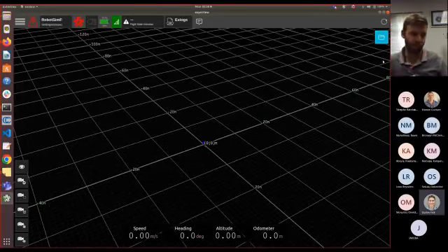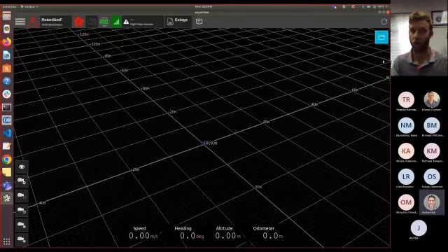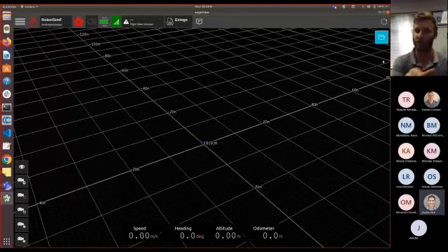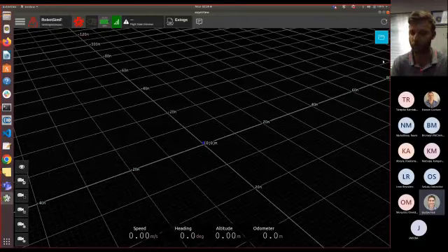So the entire premise of the flight plan is that it generates its own flight plan based on the obstacles it sees. The robot picks up, for example, walls, surfaces, and cables, identifies them as obstacles, and knows to simply go around them. So let's say there was a very small hole that was too small for the robot to go into. It won't simply fly into the wall. It will identify that there are obstacles in the way, it can't enter that space, and it will turn around and come back home. So it's not going to hit a wall or fly into any surfaces whatsoever.